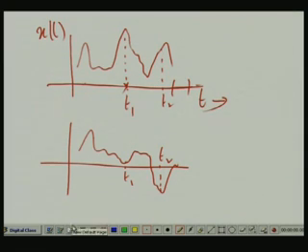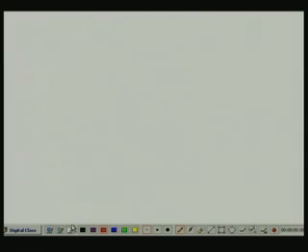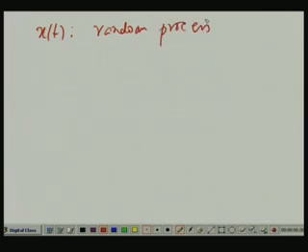This means that suppose x of t corresponds to a random process. That means there is an experiment. Every time you observe a waveform, you get some waveform. Every time you have an experimental outcome, you find some observation, some waveform x of t. Waveforms are random. A particular x of t is a sample function. These are just repetitions of what we already have discussed, and the collection of all possible x of t's is called the ensemble for this random process.